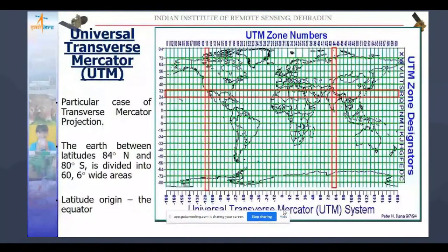So whatever analysis you see is in UTM 44 projection. Once you get coordinates from the receiver, you also have to transform them into a particular projection or coordinate system to make them uniform for all the layers. Only then will your GIS-based analysis be correct.